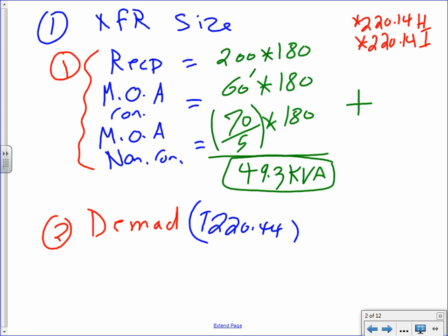Now, Jeff, since these are receptacles in a commercial building, we need to rate them, right? So if you guys go to table 220.44, 220.44 talks about receptacles in a commercial building. The first 10 kVA are sacred cow, leave them alone. Anything higher than 10, what do you do with them? Anybody remember, Aaron? What do you do with anything higher than 10K? Cut it by 0.5. Cut it by half. After 10K, you cut it by half. You guys did that one with lookout.